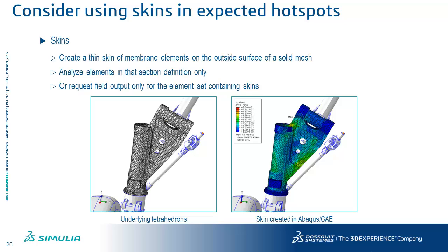It is actually a little bit in conflict with the main purpose of developing the surface stress improvement elements, but whenever you need, you can create a skin on top of the solid body so that you can extract the surface stress accurately. Then you can write the stresses on those skins only in order to reduce the ODB file size, and you can analyze only those skins when you do the fatigue calculation to reduce the computation time of fe-safe.